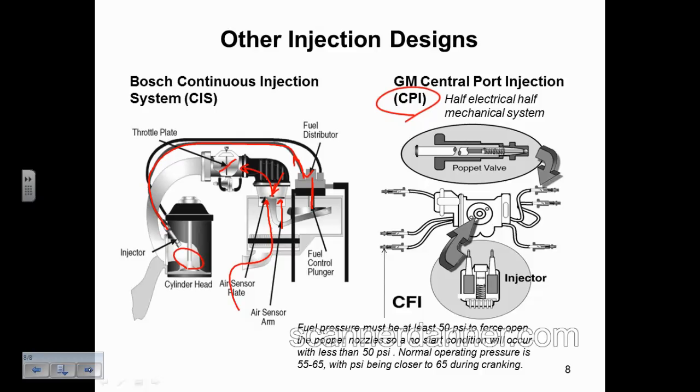You couldn't see it. When they came out with this design, it was actually really cool. It got a lot of good reviews because the Chevy 4.3 Blazer that was a TBI system, when they changed it over to this 4.3 Vortec, it said Vortec on the intake, which had more to do with the cylinder head design than the injection system, but everybody kind of calls this the Vortec injection system. It was night and day different, the amount of power these engines produced. It was a drastic improvement. They had a manifold tuning valve inside the manifold that we just talked about.